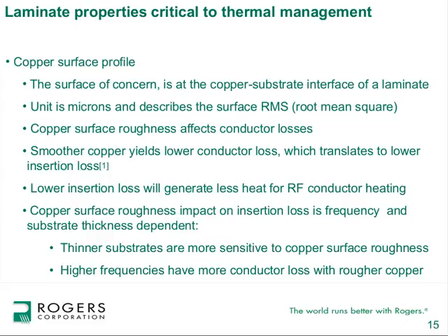We've done a lot of studies on copper surface roughness, and I've got a reference at the end here that I'll talk about a little bit. But in general, a smoother copper surface will generate less insertion loss and less heat.